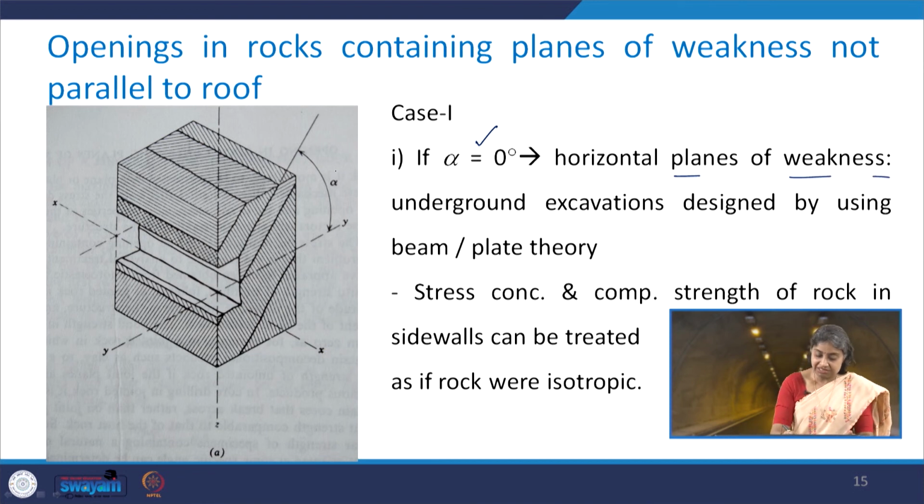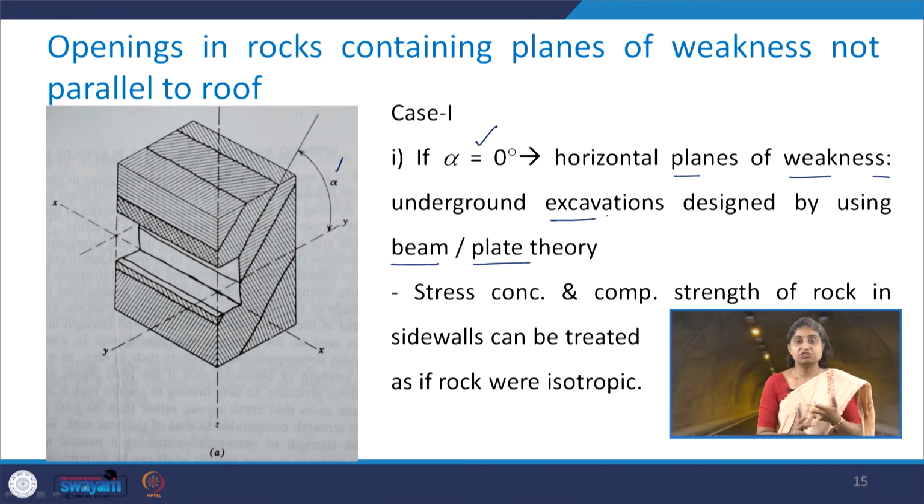In that case, we go back and use the beam or plate theory for the analysis of underground excavations, and once we know the maximum deflection, bending moment and shear force, we can design the underground excavation.